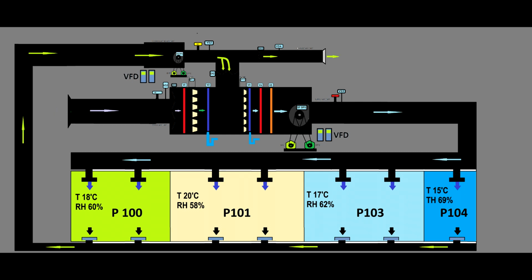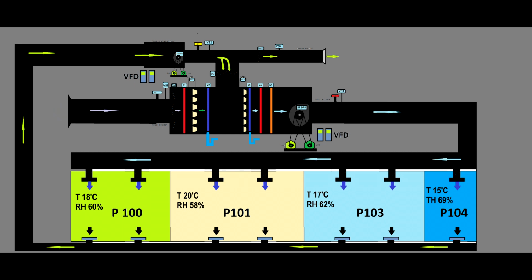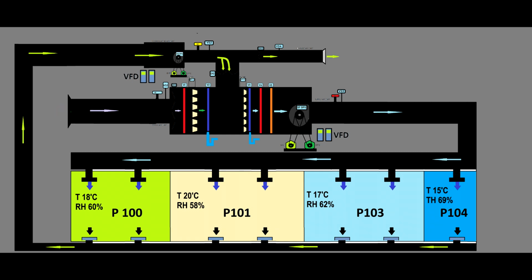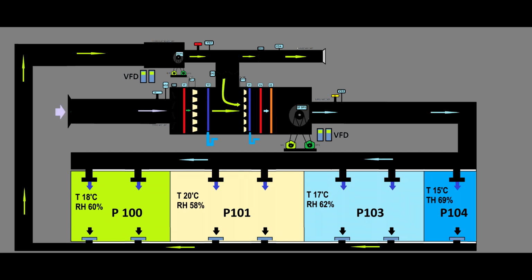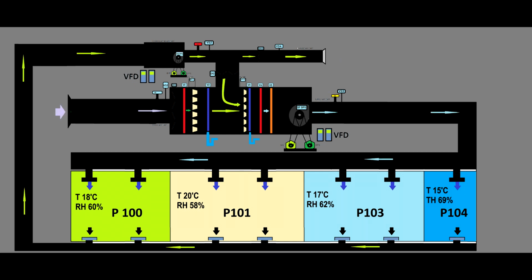But under this situation, if any modification has been done to these rooms, like bringing more equipment or changing the way it works, it will create a big hassle in the technicians' world, because this AHU will only allow me to adjust the temperature of the main airflow at the origin. So you will see these 2 probes which change their colors between red and white.